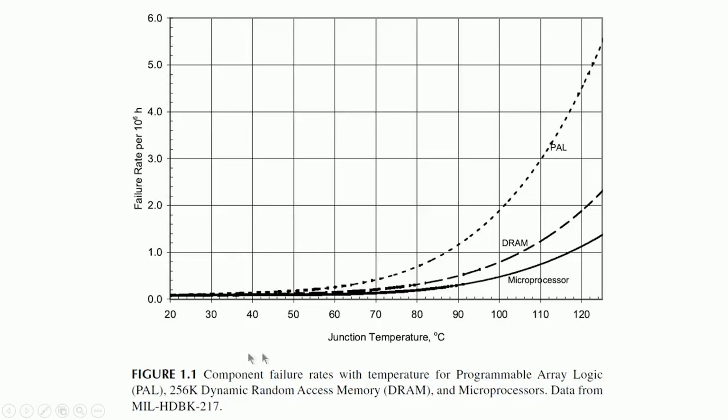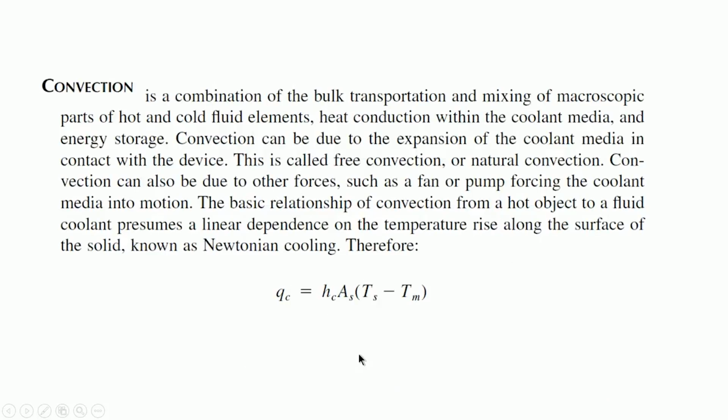It is very obvious, failure rate keeps on increasing as the junction temperature increases. So, we have various types of devices, there are logic arrays and dynamic RAMs, and then simple things. This is quite old, and probably measured and proven by the Mil standard people. Mil Handbook 217 gives various things like this. In reality, they keep changing all the time.